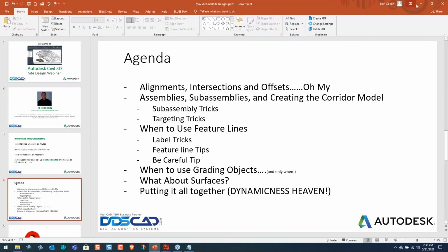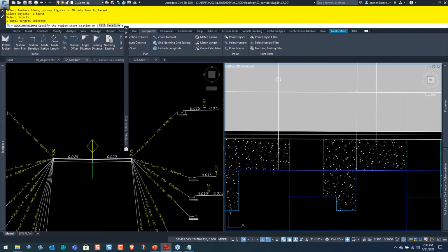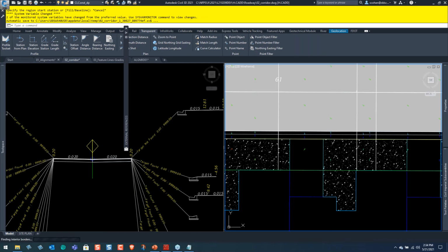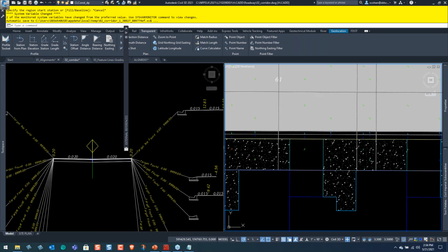Let's just hit escape here. Oh, that keeps happening. All right. And so now if I hit escape, you'll see that my surface will update automatically because it's the road surface, and then now you can see exactly how that's flowing, right? The water's going this way. It's super elevated going to the north, and obviously all the water's flowing down to the opposite locations, the opposite sides of the intersection.